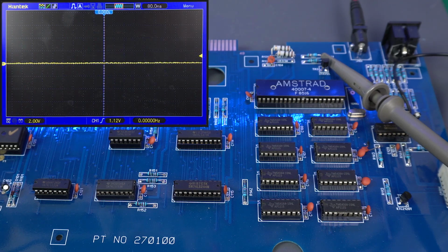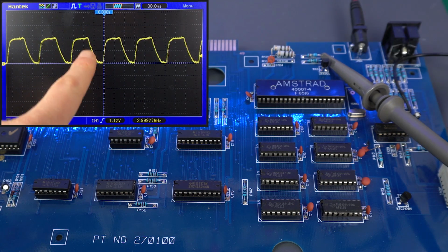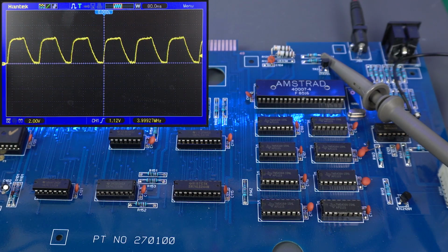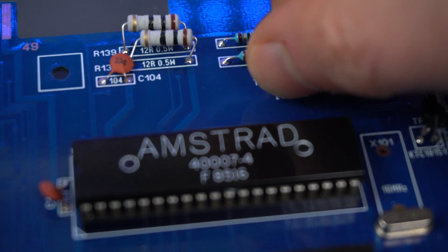And with the MOSFET transistor in place, oh, that square wave doesn't look quite right. So it looks like we need to adjust some of the resistors to get a perfect square wave like we saw on the breadboard. So we could do that, but then we would have to modify other components beyond the transistor itself, so that could get a little confusing for the bill of materials of this replacement board. So instead of that, let's try the other transistor and see if it just works straight.